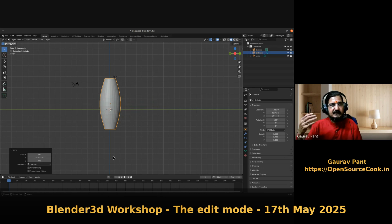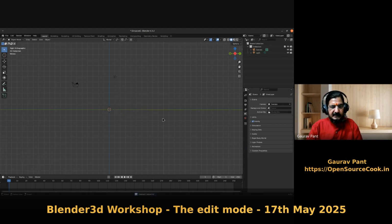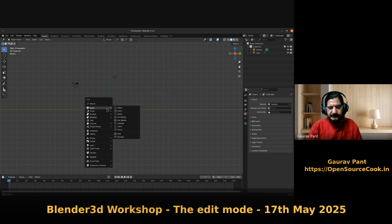Now we have seen the loop cut and we have seen extrude. Now we are going to see one operation called the inset operation, and with the inset operation, we are going to see how we can create that interesting cube or something. But before that, let's take up one example of how we can create a simple table and chair out of a simple cube. Let's add a mesh, let's add a cube.